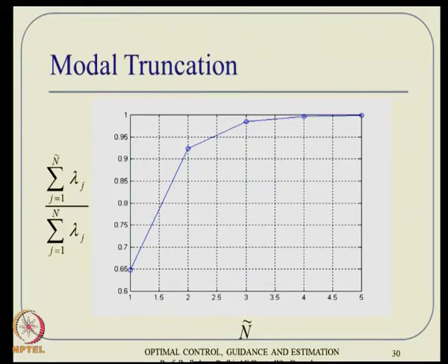If it is close, this truncation will happen very quickly. But this picture tells you everything. Even though we started with 200 snapshot solutions, ultimately it results in 5 basis functions because of this lambda convergence behavior, and hence the dimension of the lumped parameter system happens to be just 5.